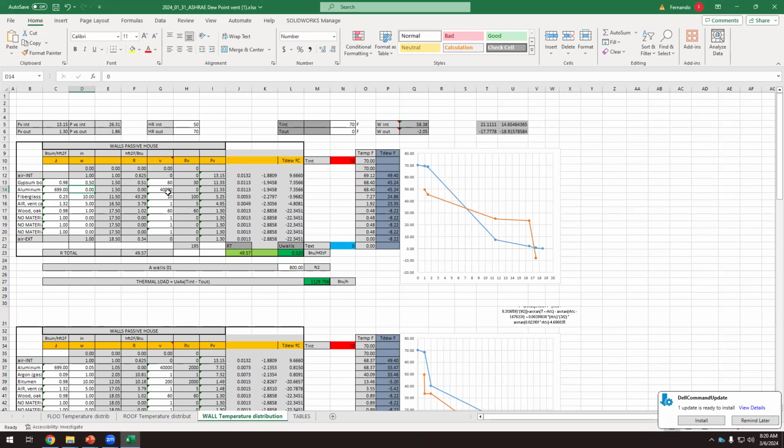It's just a film, it's a tape, so it doesn't have any thickness, but this bluish or greenish layer that they stick to the OSB board, this is the vapor retarder. It's something extremely thin, so we can type here 1/10 of an inch. It's nothing, but that's the effect that it causes.